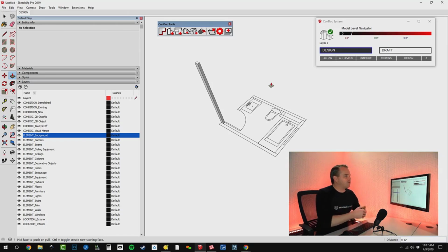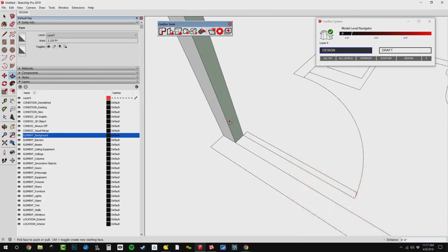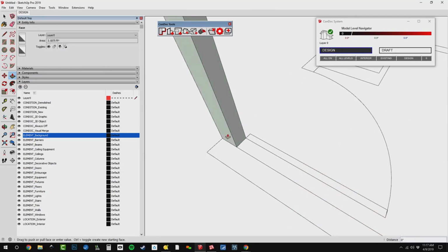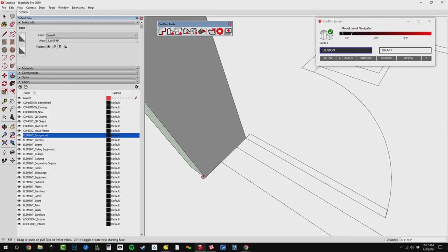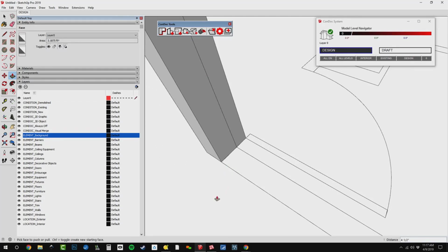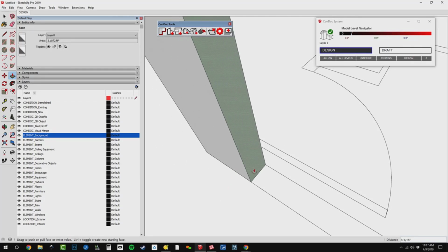So this way, as we go along, we can turn the corners, we can leave all the verticals that we need for our door and window openings. All right, so I'm going to be using the push-pull tool, and I'm going to be tapping Control to leave a copy of the starting face behind. Let me show you what that's all about. All right, so I'll zoom in here. I'll click once to start, move my cursor, tap Control, and see how it left that edge going straight up, and then I can snap to this point. This means that I can easily turn the corner.